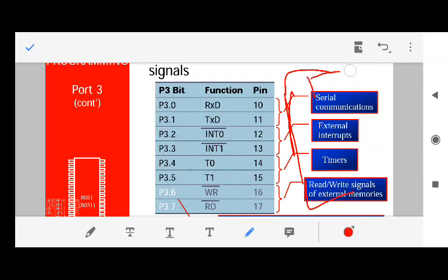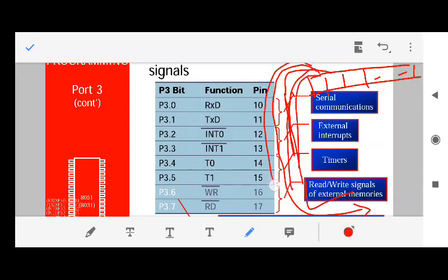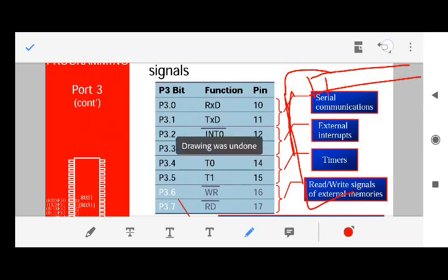If the data is, let us say, 16 bits, then those 16 bits are assembled like this: first bit, second bit, third bit till the 16th bit, and bit by bit is moved through that single line and received at the receiver. First bit will go, then second bit, then third bit, then fourth bit will go through the same link. This is known as serial communication. By using this way, you can move any size of data.